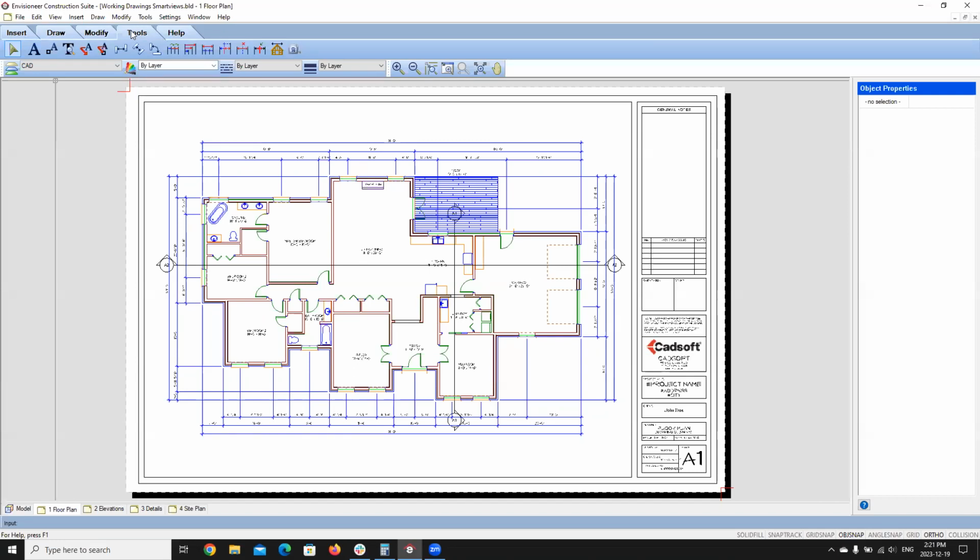Just a quick note here to remember that the extra lines and hatch that you add here are not linked back to your model. So any modifications you make here will not be reflected in your model or any subsequent views you insert. If you want to make changes other than line work changes, it is best to make them in your model view first. Changes you make in your worksheet view will mainly be for line work changes.